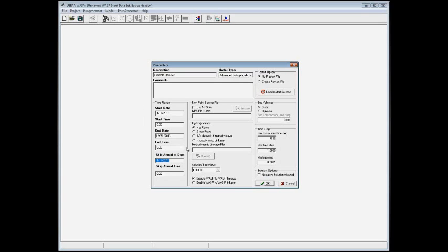The other options that we have on this screen are setting the hydrodynamic, or how the flows are going to be calculated in the model. There'll be a little bit more about that in the flow lectures that'll be developed. I'm going to be using the 1D kinematic wave, which is going to allow WASP to calculate the flow through the system. I'm going to leave our solution type to Euler.